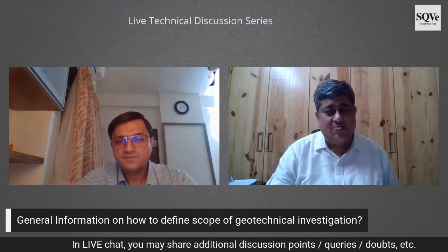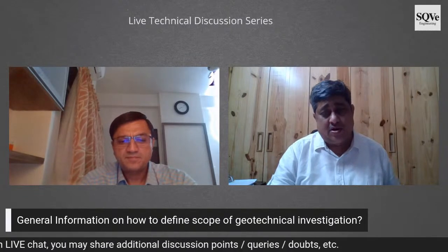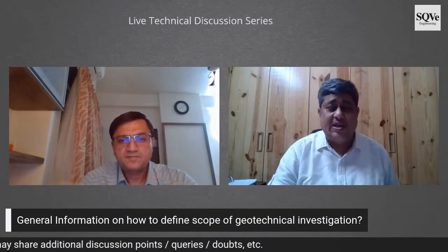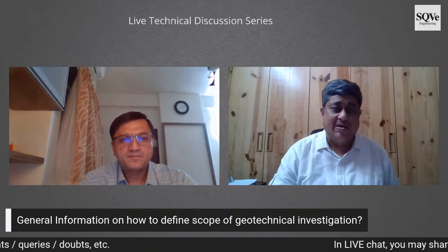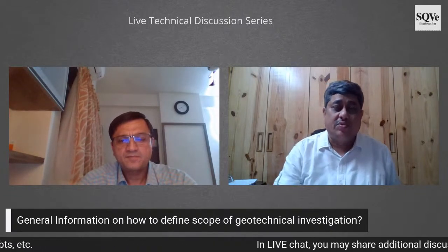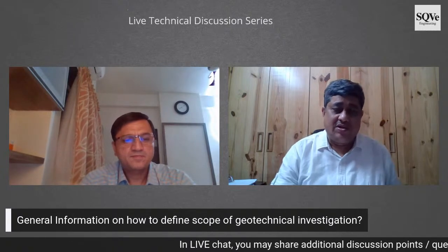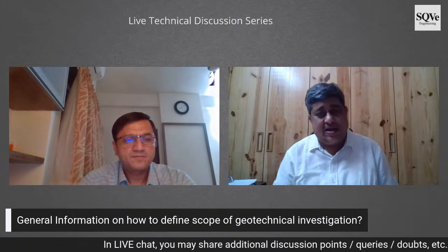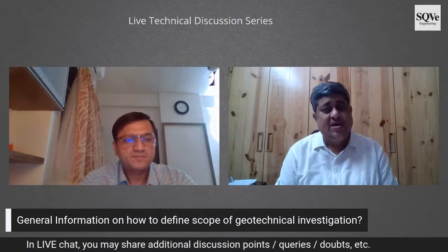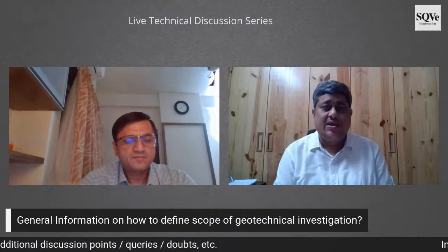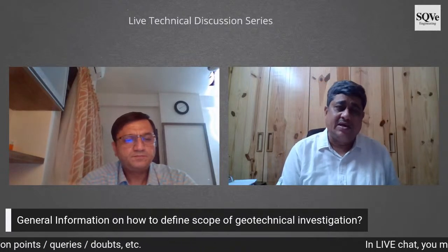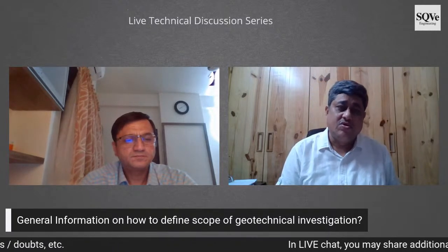Like suppose I have to go for flooding the soil in a very sensitive soil where the rainwater is readily available and stays there for 2 or 3 months. All these things are data which need to be shared with the geotechnical investigator, and then both of them should work together and find out the parameters and the approach to solve the problem.